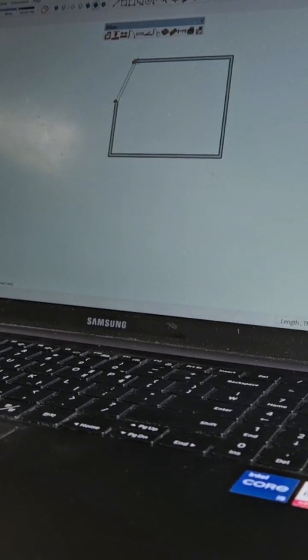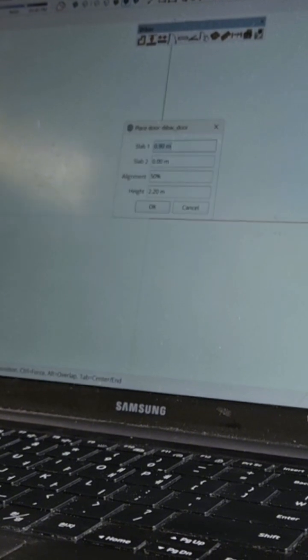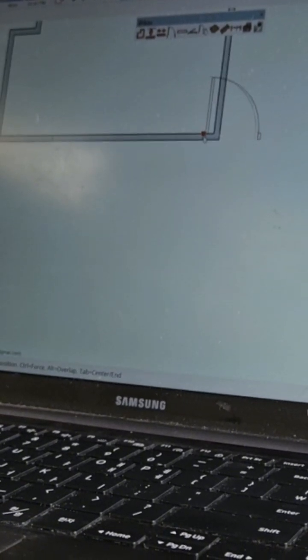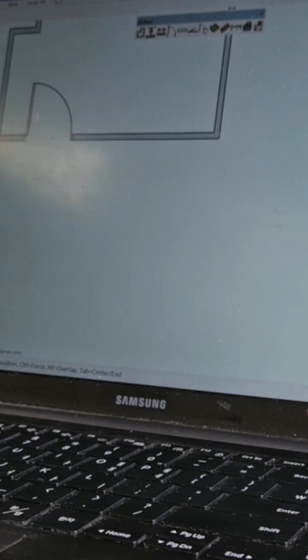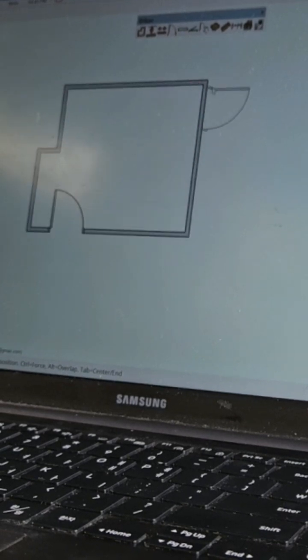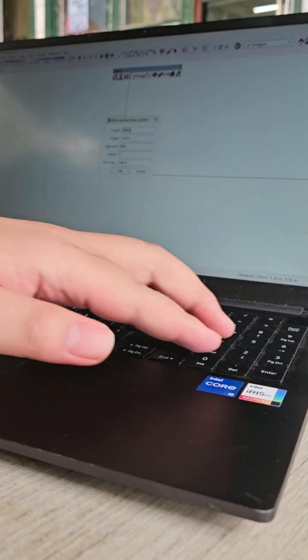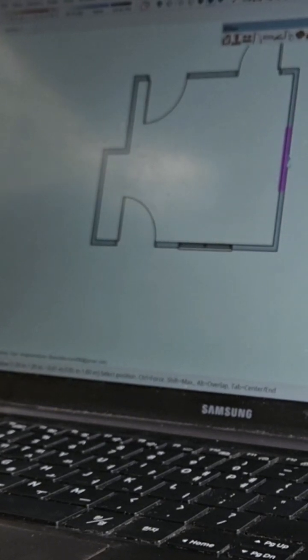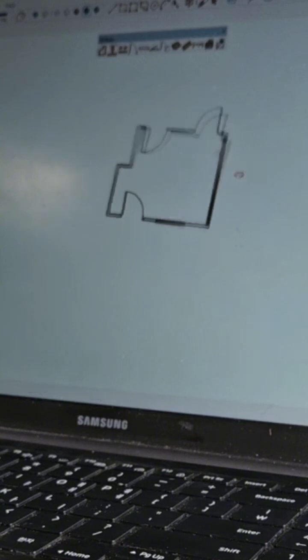For example, like this. And you can actually auto cut doors. For example, I want a 90 width door. It goes pink in order to cut the door. And it automatically snaps with the walls that you make. For the window, I would like 1.2 meter length. And if you would like the whole window to stretch or to span, just click on Shift. There you have it.